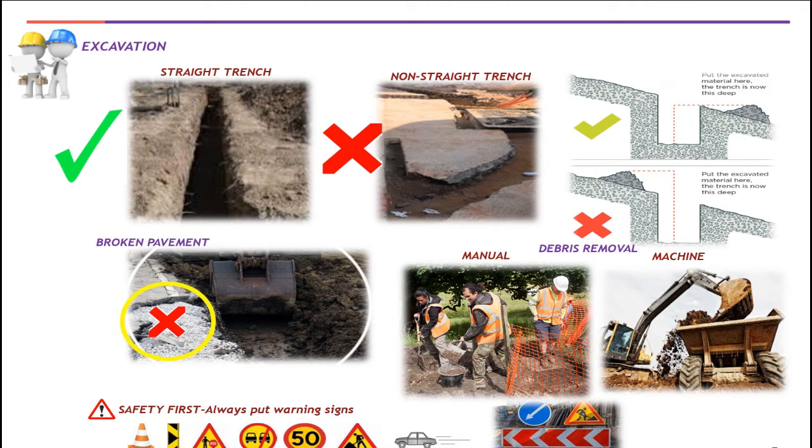Always avoid breaking the pavement beyond STC requirements. You also need to remove debris from excavation immediately where there is frequent traffic in the area. Where there are existing utilities, the trench must be 50 mm away from these utilities. Inform the owner immediately of damaged existing outside plant utilities if this happens.